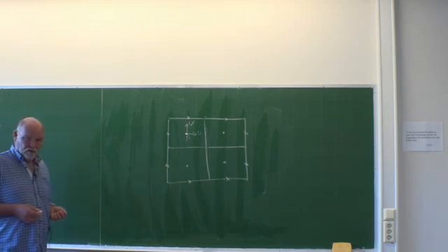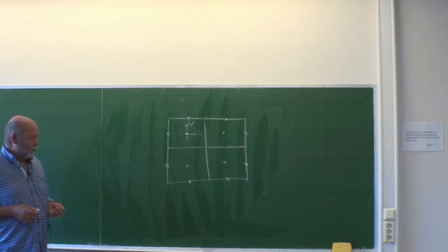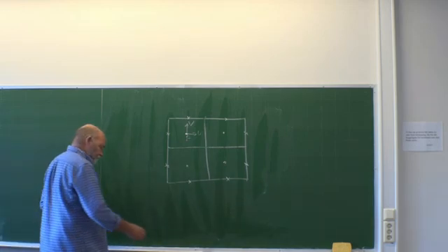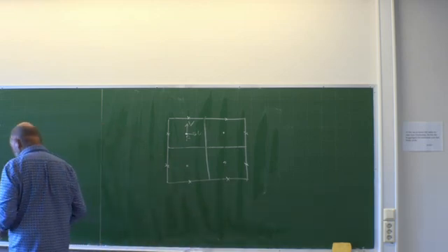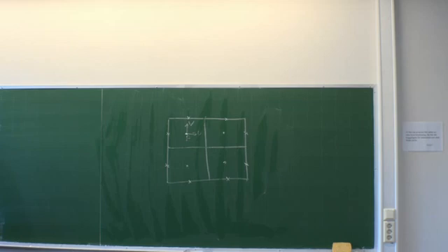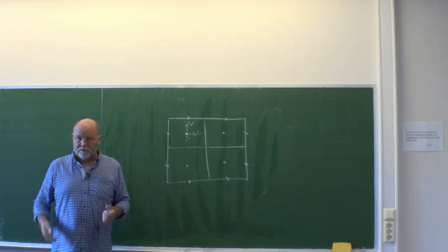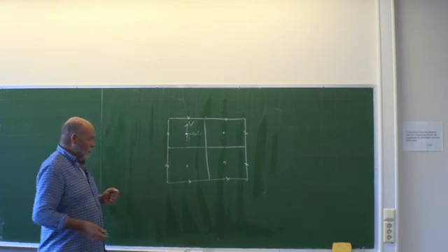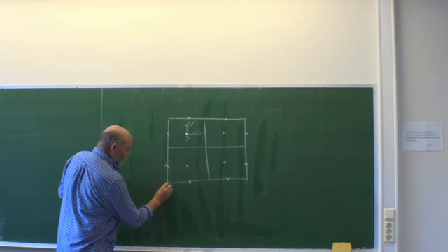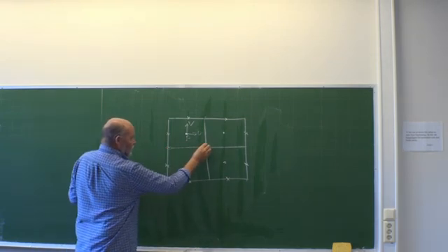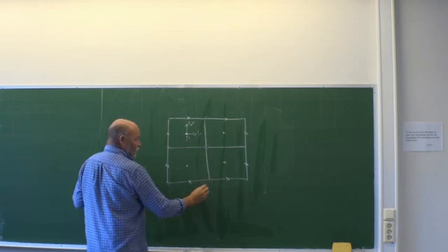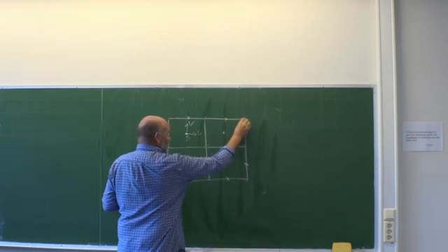I had 73. So what's really happening here? Sadly, what's happening is that OpenFOAM interpolates. The results you get are located now in the cell corners. This is what you get when you just save the data crudely.